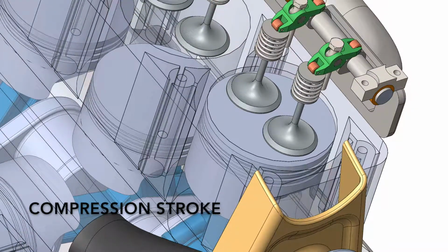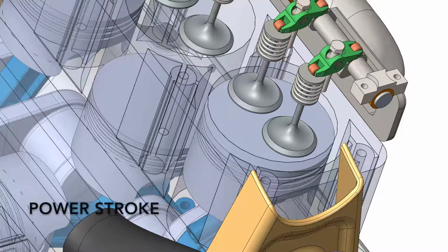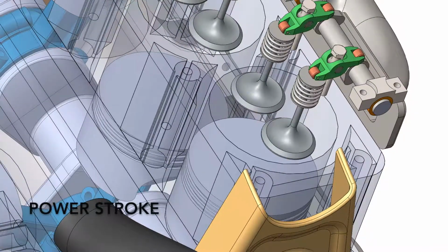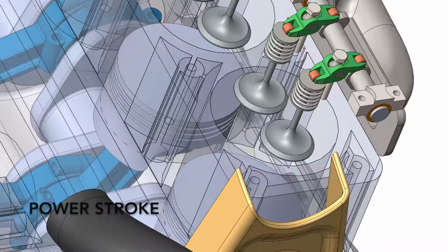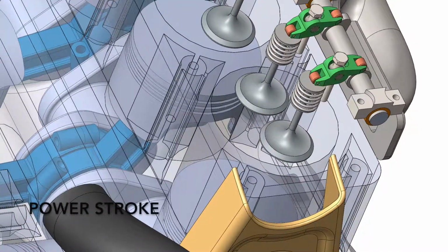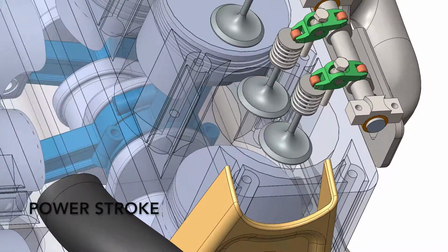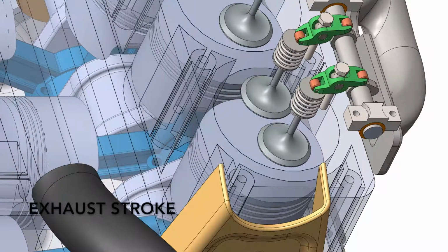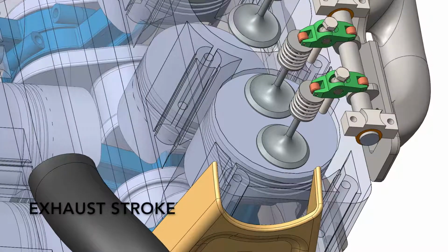This causes the third stroke of the 4-stroke process, the power stroke. The piston moves down into its chamber as the volume increases and the pressure decreases. This process can be estimated as both adiabatic and isentropic as estimated by the reversible Otto cycle. The fourth stroke of the 4-stroke cycle is the exhaust stroke, where the piston moves up, decreasing the volume, while isobaric, causing the exhaust to leave the chamber through the exhaust valve.